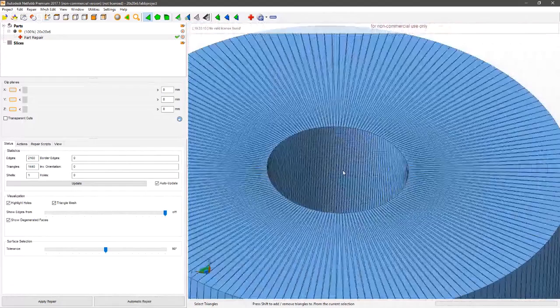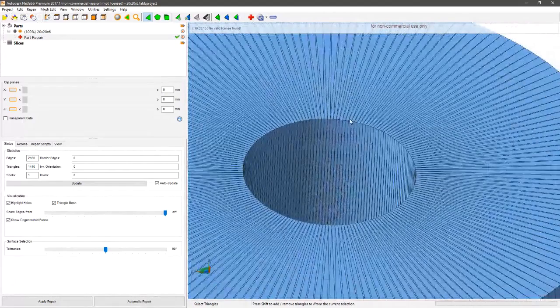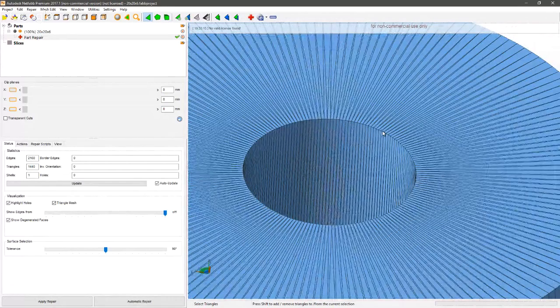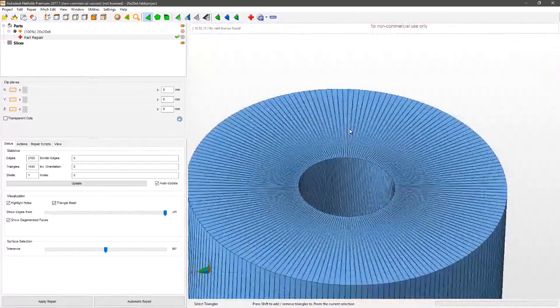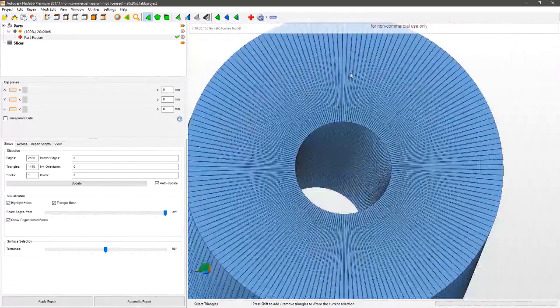So essentially, this small section, these are down here, it's twice as much even, has maybe 30, 40 lines of G code that it produces, that the machine requires to print this. So just this short section is going to have 30 times or more processing power requirements than just a straight line of the same length.